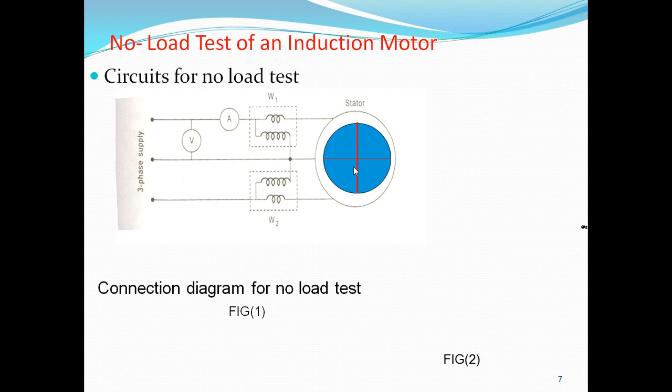When the motor is running on no load, it develops only a small fraction of full load torque in order to overcome friction, windage, and iron losses, in addition to the small amount of copper loss in the stator winding.